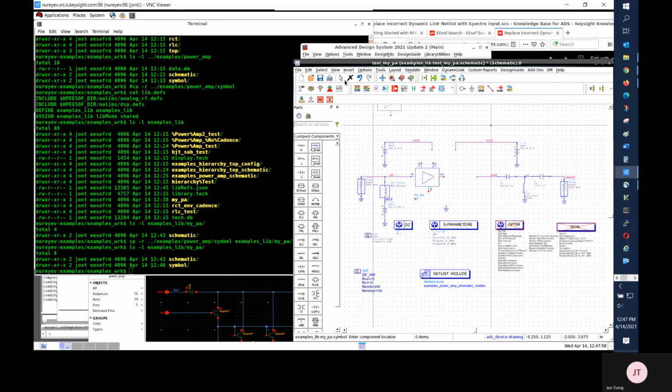Dynamic link scales the Cadence symbol by a factor of 2. You can modify the scale factor, but I have never seen anyone do it. That's why the blank area in the middle of the test bench is 4 times larger than the symbol. Both X and Y are magnified by 2. Once I'm done with all the connections, I'll save the design, and it's ready for simulation.